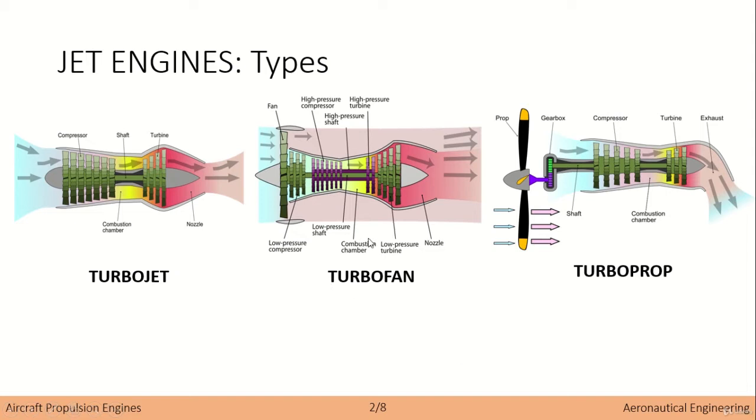Turbofan, the difference between the turbofan and the turbojet is that instead of having only one flow, we will have two kinds of flows. First, we will have something very similar to the turbojet in the interior, but we also have some kind of flow on the exterior, like this, which will actually be named the cold flow. So this will be hot flow, because the exhaust is at hot temperature, whereas this will be named the cold flow. The idea is that we have greater efficiency at subsonic flight due to a fan.